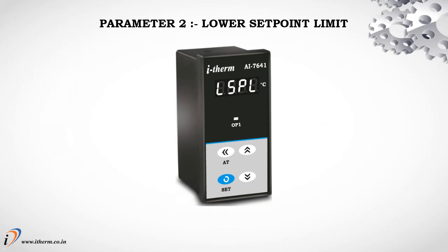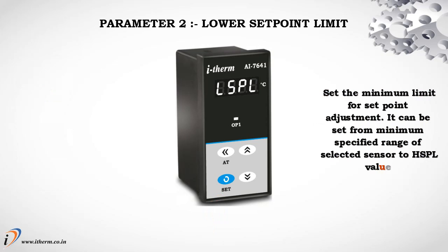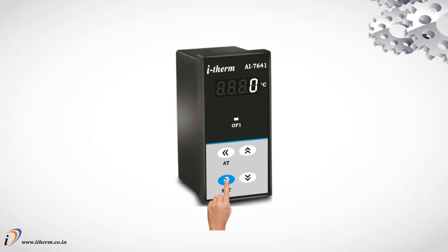Parameter 2, lower set point limit. Set the minimum limit for set point adjustment. It can be set from the minimum specified range of the selected sensor to the HSPL value. Default LSPL value is 0.